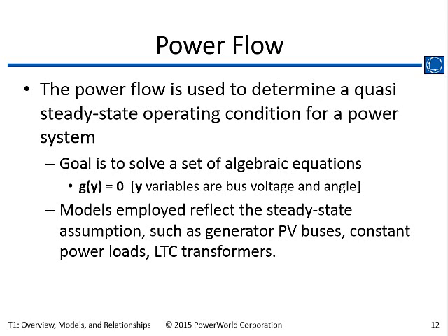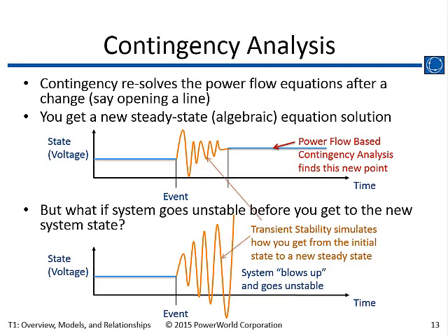That's pretty straightforward to do, and that's what we teach in undergraduate power system analysis classes. But then when you develop commercial power system analysis tools like PowerWorld, you have to get into the details of how do you model these LTC transformers, what equilibrium point are they going to get to. Generators are PV buses, but there's a lot more to it because you've got to deal with how do the switch shunts play in, how do the phase shifters play in. We've put a lot of enhancements into PowerWorld to deal with this, some of them funded by you guys. Okay, so power flow is pretty involved, but it's looking for an equilibrium point.